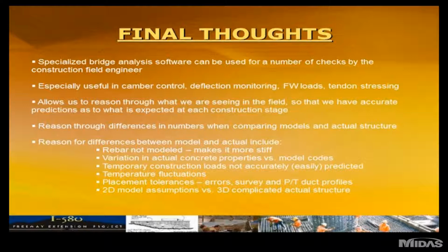It allowed us to reason through what we were seeing in the field, so we could have a better understanding of what was predicted and what was to be expected. Again, going back to the pier deflections, the tendon elongations, the cambering differences with the varying construction stages, there were reasons noted for the differences between the model and the actual structure.